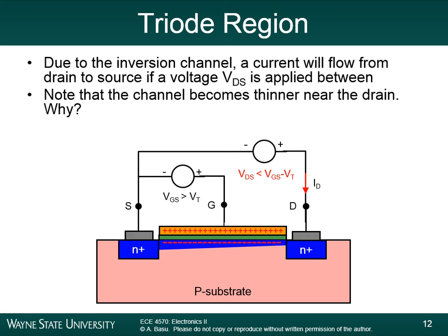You're reducing the field at that corner where you're applying the additional bias right to the drain. Absolutely, you end up reducing the field. Yeah, very good. So when you apply a bias to the right side, you're applying a voltage to the right side of the material, and a current flows through here.